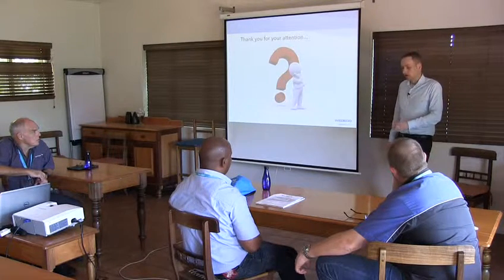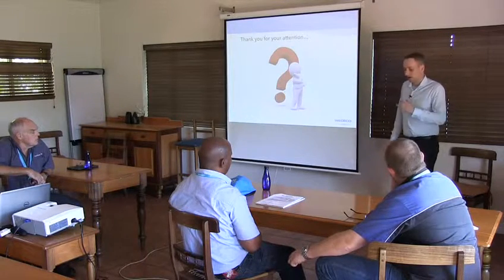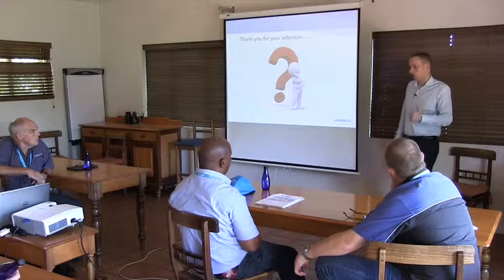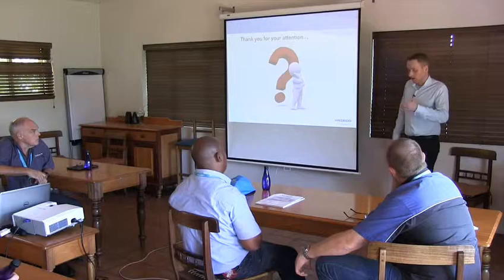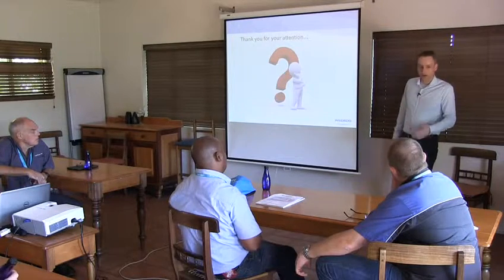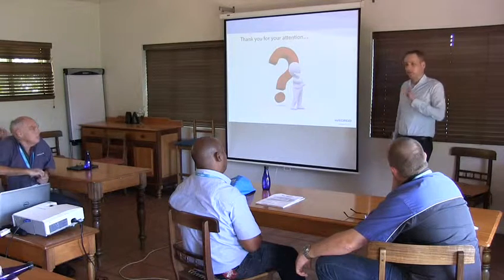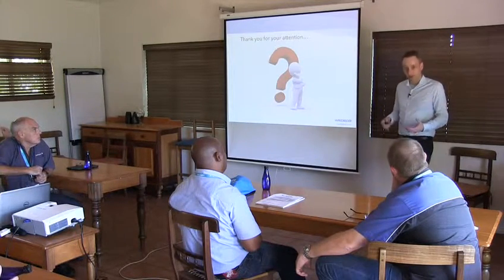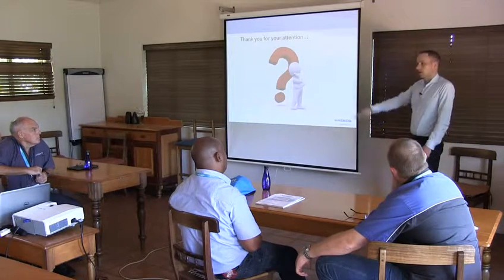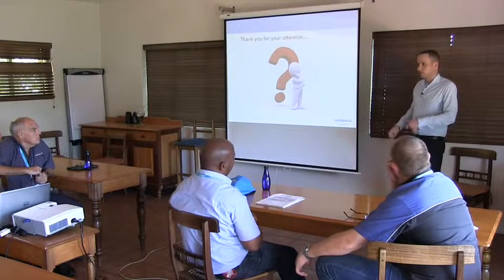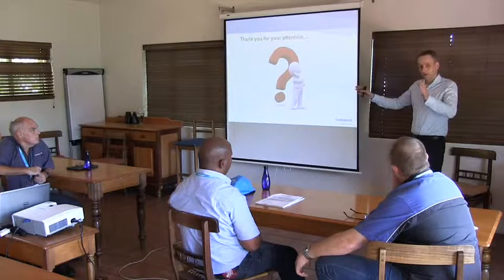For a medium pressure system, you have lamps that have a lot more mercury inside, and operate at a higher temperature. There you get not only the spectral light emission from the mercury, but also from all the other stuff inside the lamp. So you get not only the 98% peak at 254 nanometers, but also a huge range of all the UV broadband light.